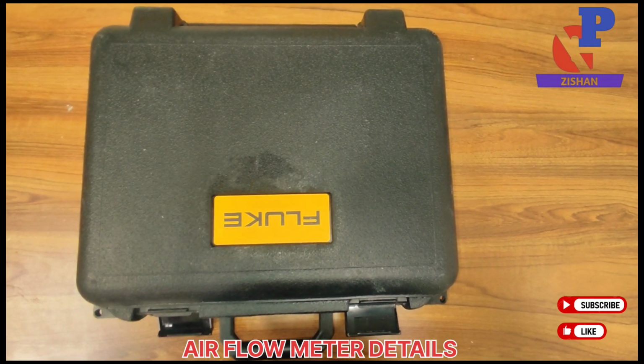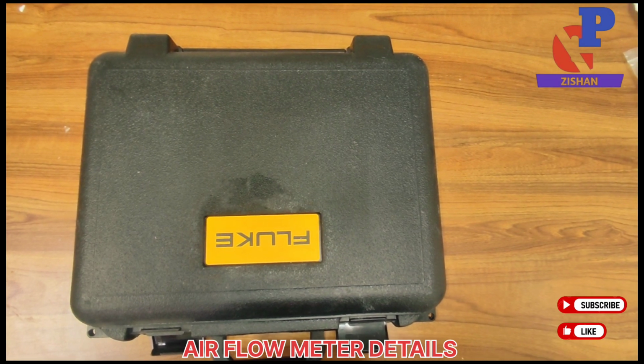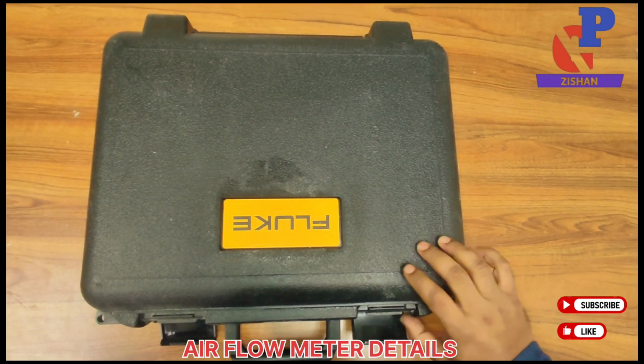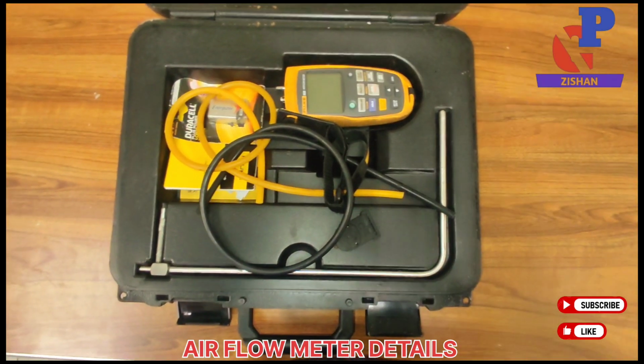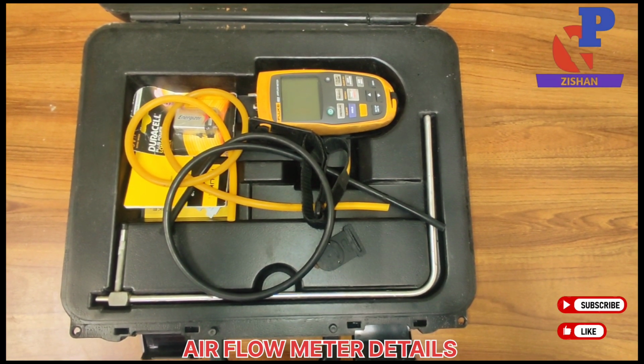Today we have another instrument, and this is called a Fluke airflow meter. From this meter we are going to calculate the static pressure, differential pressure, flow volume and velocities inside the duct, or we can check the differential pressure across a coil, filter or blower.